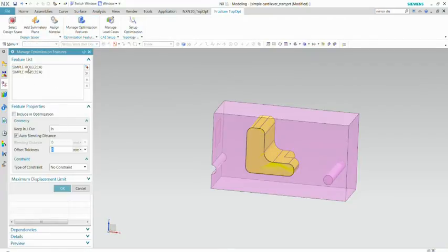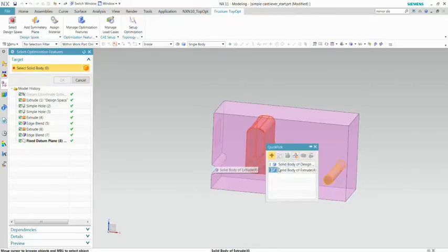Further on, we're going to say that around that central hole that you see highlighted over there on the left, that we want at least 1 millimeter of material. For example, that we want a full zone for an axis. And at that location the part is also fixed, so that the part cannot move around that hole. We're also going to define an offset around the right hand hole. And finally, I'm also going to add the shape in the middle, the yellow one.